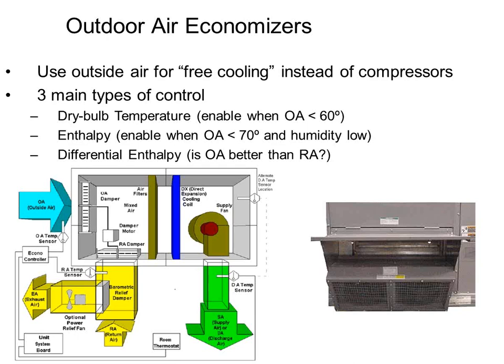Dry bulb economizers are most commonly used. The issue with enthalpy economizers, one, technicians are a little scared of them sometimes, and we do economizer classes for techs to help them out with that, both at our office and at the union to make it easier. The other side of the equation is enthalpy sensors historically drift out of calibration, and it kind of becomes a pain in the butt. So I've got a rule of thumb that I've been using for several years now. If the rooftop unit, and I'm going to save more energy by doing the enthalpy economizer instead of the dry bulb, let me just say that.